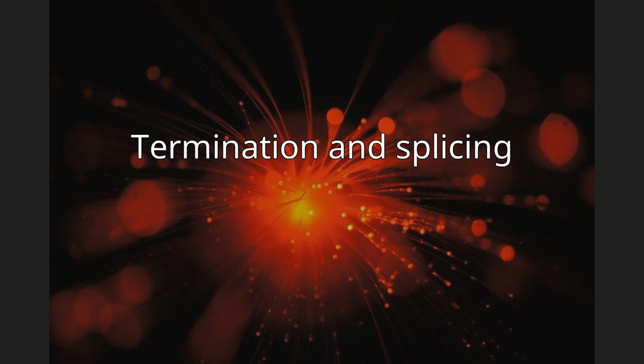For single-mode fiber, fiber ends are typically polished with a slight curvature that makes the mated connectors touch only at their cores. This is called a physical contact (PC) polish. The curved surface may be polished at an angle to make an angled physical contact (APC) connection. Such connections have higher loss than PC connections, but greatly reduced back reflection, because light that reflects from the angled surface leaks out of the fiber core.